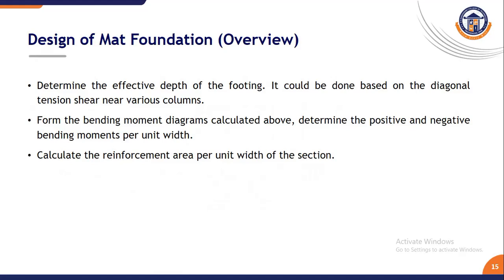Design of mat foundation also includes the effective depth of the footing we need to calculate, and also the bending moment diagram we need to calculate before designing of mat foundation using STAAD Pro or any other software, and also calculate the reinforcement per unit width of section. Okay, all these things we need to calculate before designing of mat foundation.